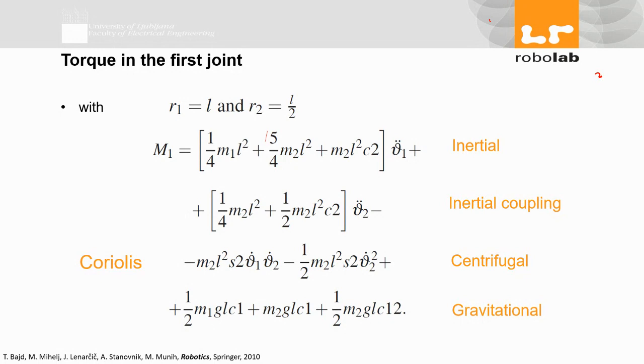That's fine. If I give you M1, L1, theta 1, speed, gravity, if I give you different components, and ask what is the inertial component of this torque at motor 1, you should be able to calculate that, right? Because you have the equation.